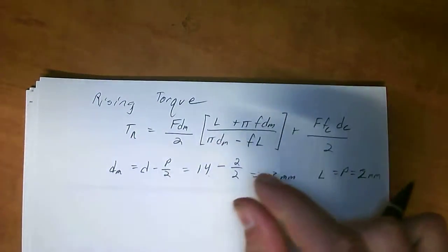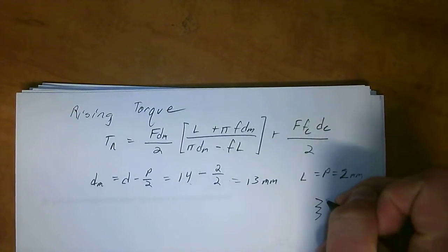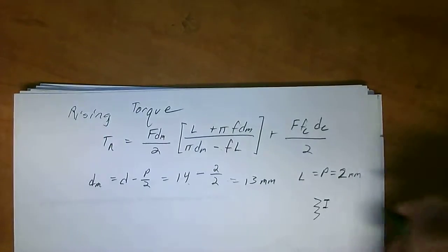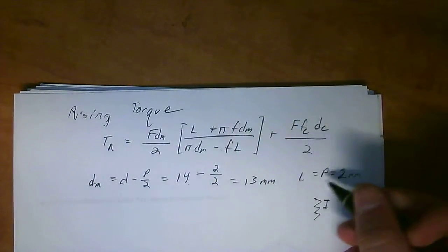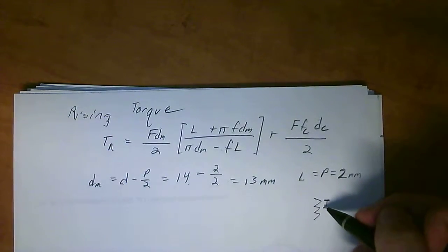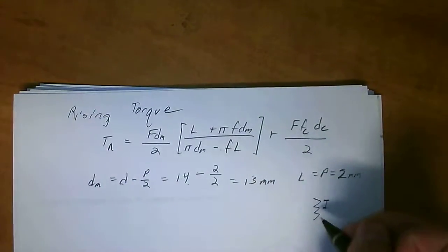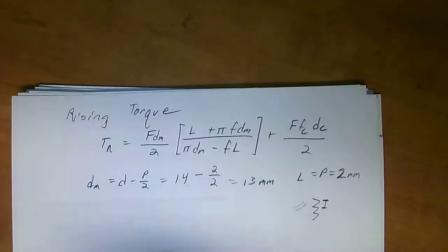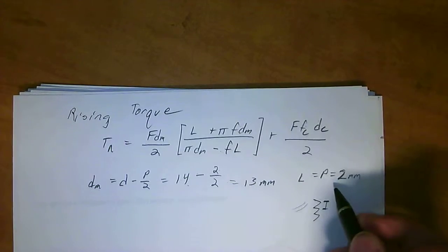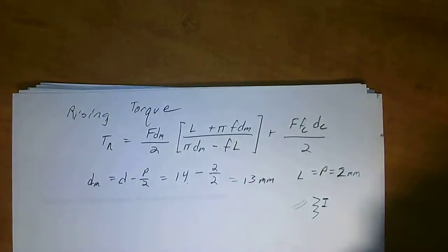So it's basically, if you have a bolt like this, L is from here to there. But that also happens to be the pitch. The pitch is always from tip to tip, basically. But L can vary if you have a double threaded system. So like you have a thread here and a thread here, but they're not the exact same thread like a normal spiral. It's two coming down. So that's when the L would be different from pitch. But normally your professors don't really bring that up. So in this case, L is equal to pitch.